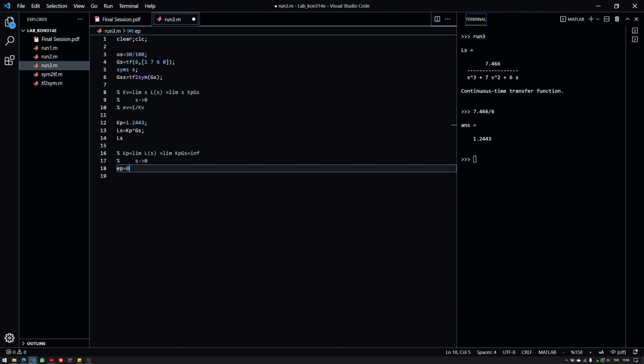And the way that this works is that we have a type 1 loop transfer function here. So the type of this is 1. So it means that we have a pole at the origin. So this is basically the magic here. It's not the p-type controller, it's the integrator in the loop transfer function, or the pole at the origin of the loop transfer function that achieves the step type input tracking with 0 steady state error.